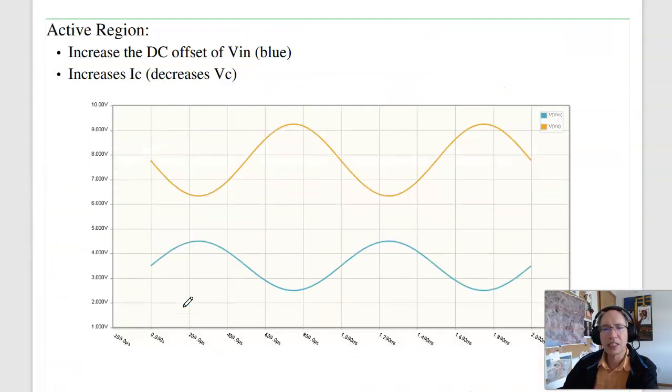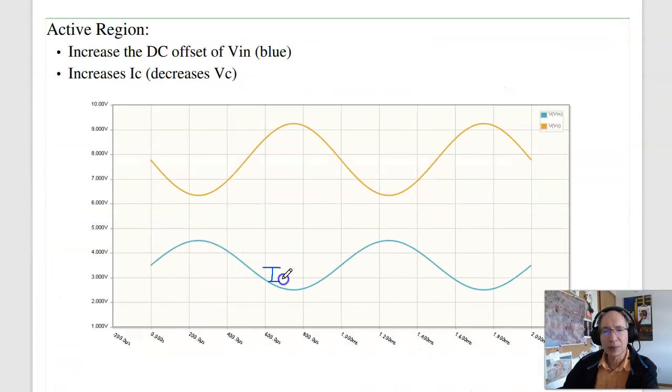And you can see that in Circuit Lab. If this is your input right here, it's nominally about, it looks like about 3.2 volts. Here's the output voltage. That's your voltage at the collector. Sine wave in gives you sine wave out. That's an amplifier. It's also inverting. That's a property of this amplifier. The output has a minus sign in it. As the input goes up, the output goes down. But that's what we do in 321 analog electronics.